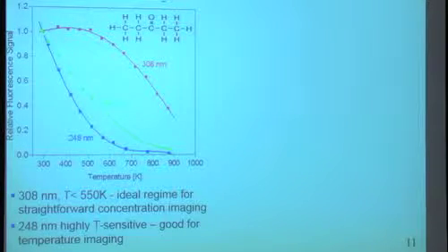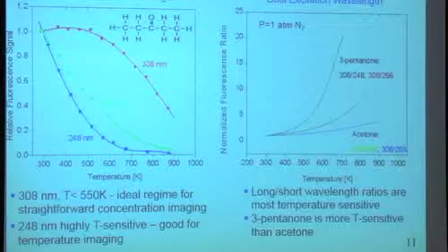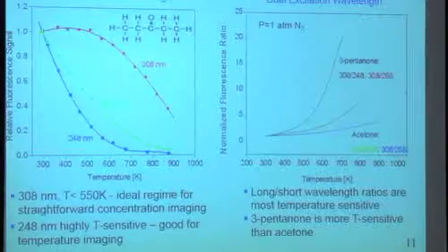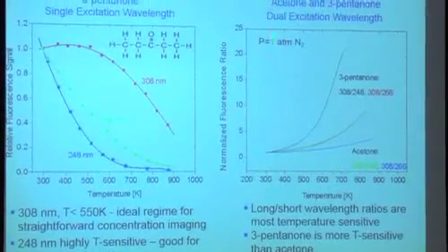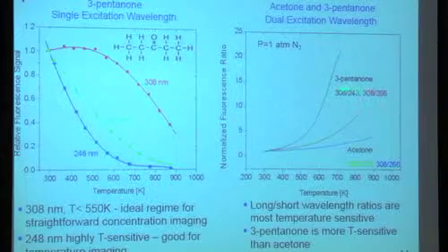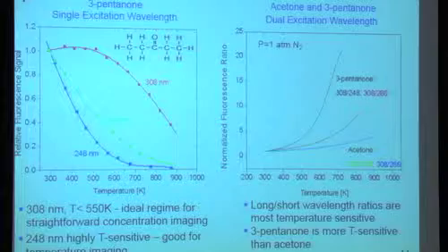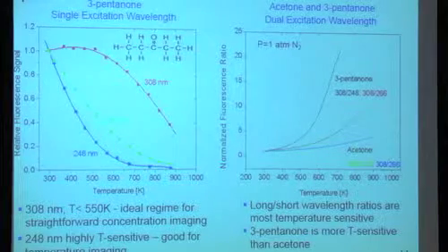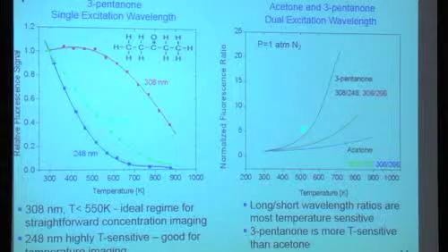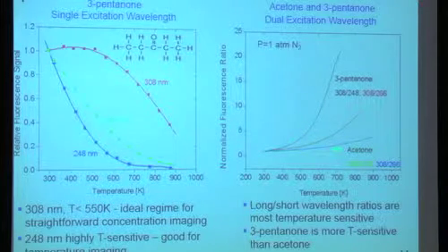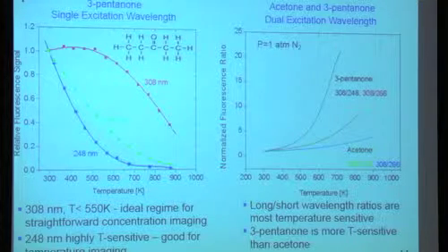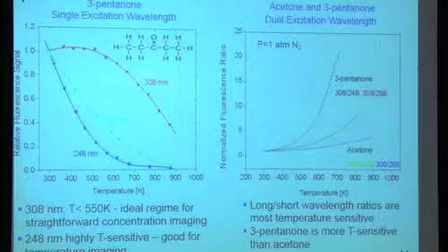So we're starting to come to grips with compressible flow fields where there's variable conditions. So now you want to measure temperature. The thing to do, we always take ratios. So now you take these signals and you take certain ratios. So what if I excite at two colors, 308 and 248, bang, bang, take the fluorescence, take the ratio, I can get that it's extremely temperature sensitive. So basically you're illuminating the same molecules. Only thing that's changed is sigma and phi.